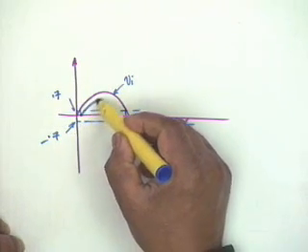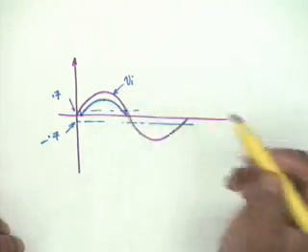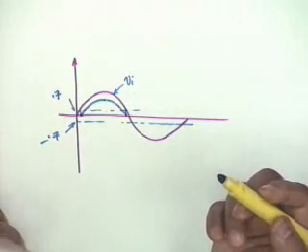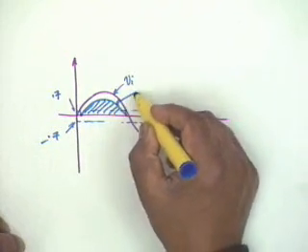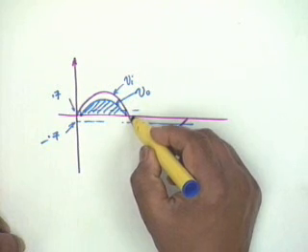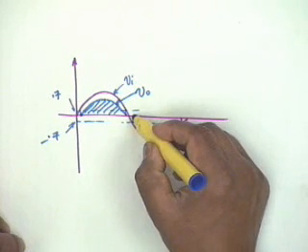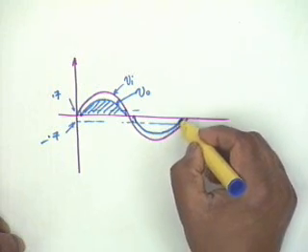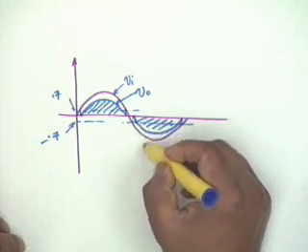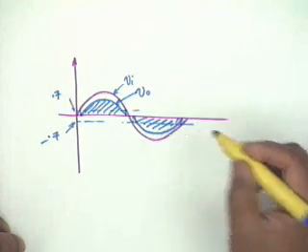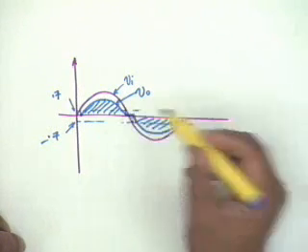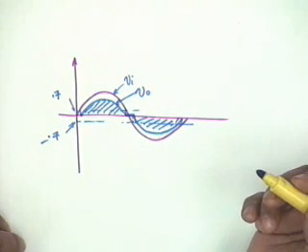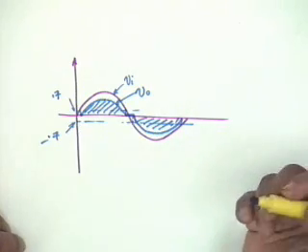So it would be something like this, where the two curves are exactly parallel with a difference of 0.7 volt, and this would be the output V0. On the negative cycle the conduction will start here and you will get a curve like this, which is also exactly parallel to the Vi curve, but with a difference of 0.7. Okay. And this is the region where there is no conduction, and therefore you get a distortion, and this, as I had told you, is the crossover distortion.